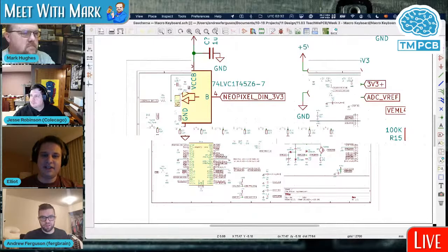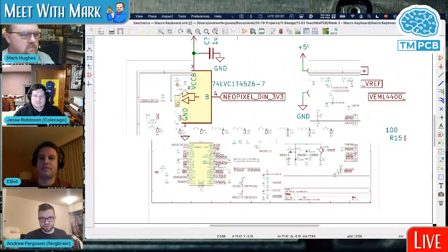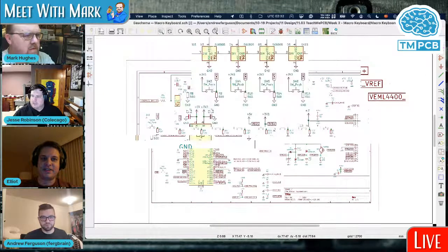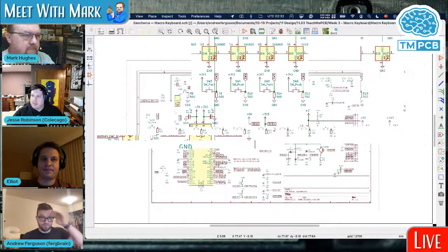So if I put a net label like there, did I forget to do it, or would I probably have just put it at the end, maybe. Yes, I completely agree with that. But I wanted to make sure I was actually doing it. Now, does KiCad give you a net connectivity report? Yes. Okay. Yep. And it will complain.